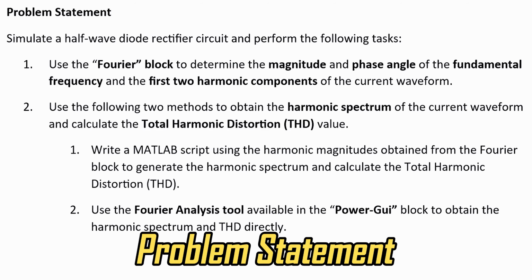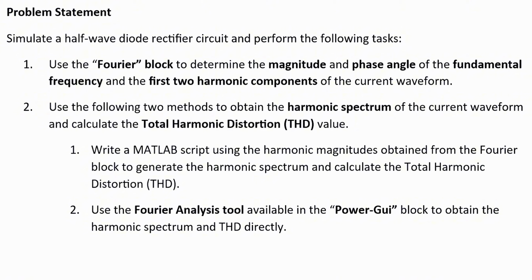Problem statement: simulate a half-wave diode rectifier circuit and perform the following tasks. 1. Use the Fourier block to determine the magnitude and phase angle of the fundamental frequency and the first two harmonic components of the current waveform.